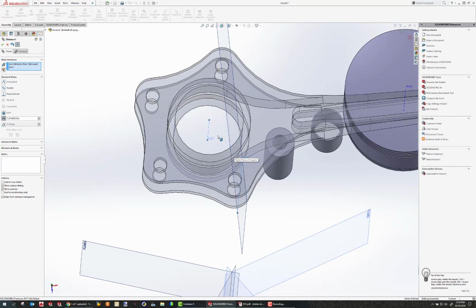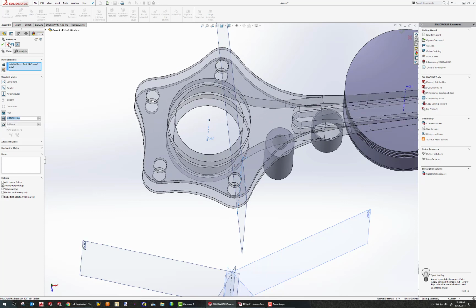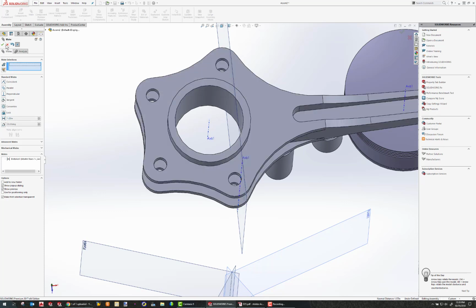So as I look here, this axis is 40 millimeters from this axis. So no matter what, this center line of this master rod is going to spin around that axis that I created as my first step. So 40 millimeters, SolidWorks converts for me. I can click the check.